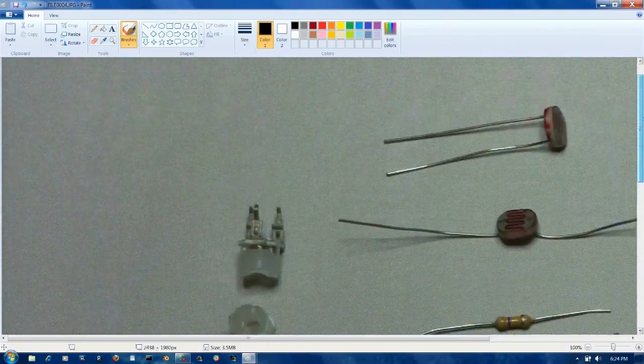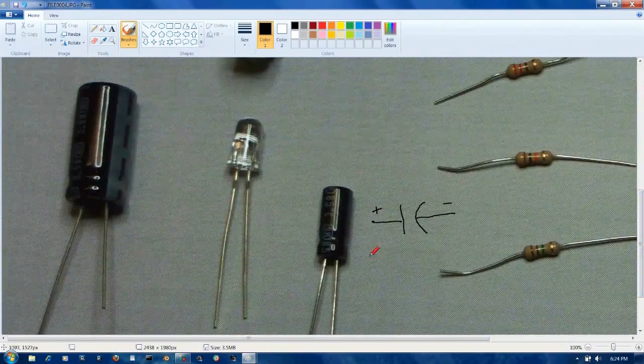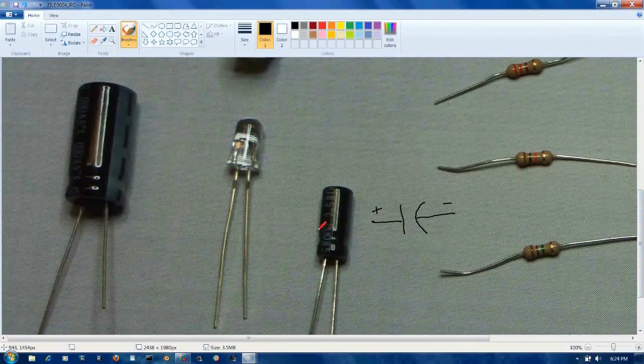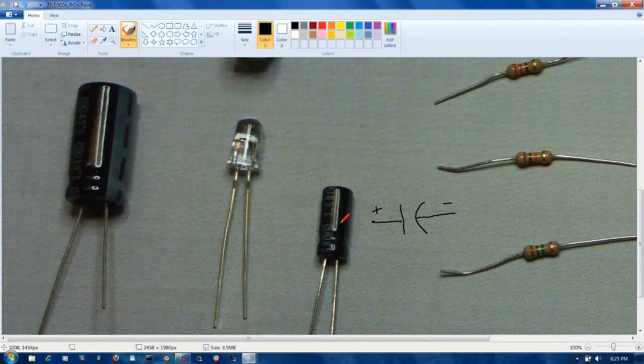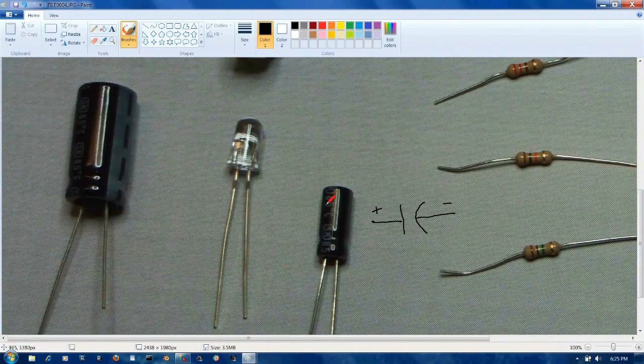I don't think I need to do a whole tutorial on capacitors. They just store electricity. I will mention a couple of things. They'll have ratings on them for volts, and you actually can't see the ratings on it. So maybe I will have a brief tutorial on capacitors after our first lab. You can't go over the rated volts. Most of these are like 30, 50 volt, and we're going to be supplying 9 volt to them, so it's not an issue.